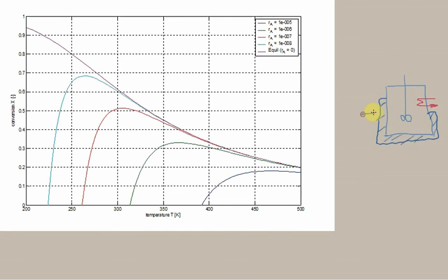So we could have a high flow rate of cooling water here. And so obviously this is a batch reactor. There's no flow of reactant and product across the walls here, but there's this jacket. So we can flow things around the jacket without disturbing the reactor content. So we get good cooling heat transfer here, and we could add a heating coil here also.